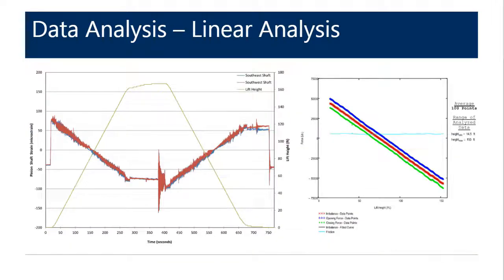Here is the data analysis for that fundamental linear equation. The strip chart on the left and the balance analysis on the right are from a tower drive vertical lift bridge without any of those compensation machinery, either auxiliary counterweights or balance chains. Behavior of the balance throughout operation is linear.